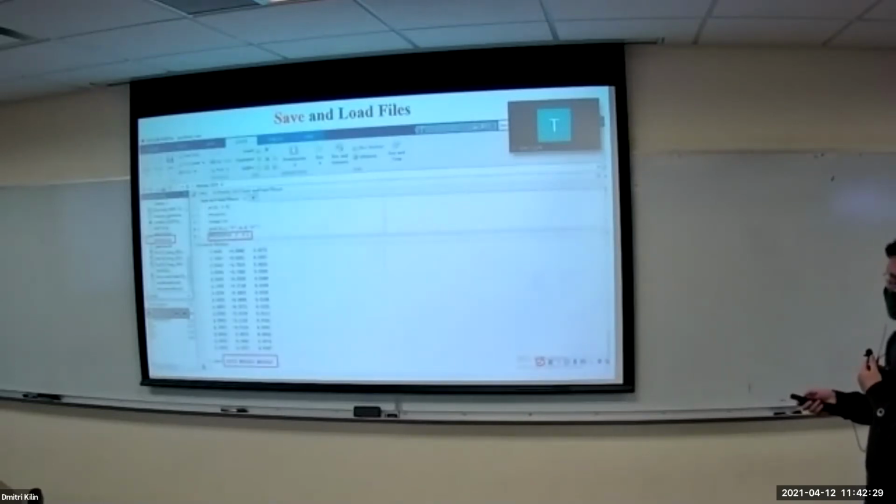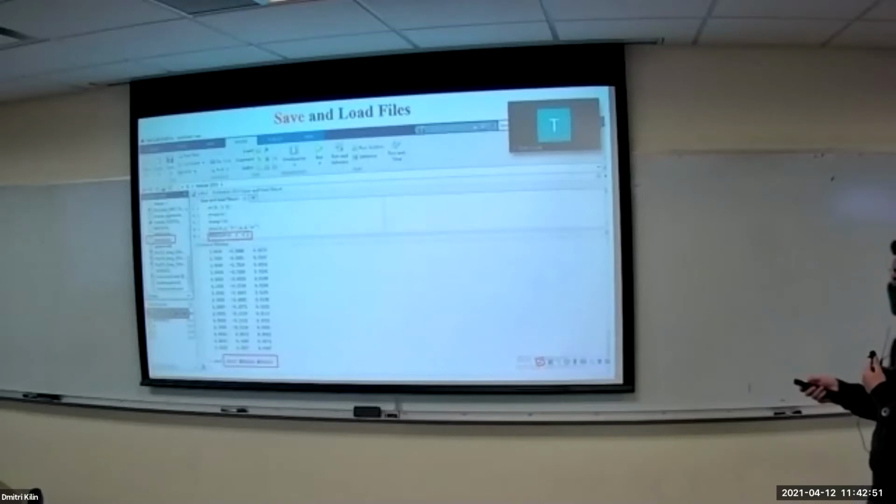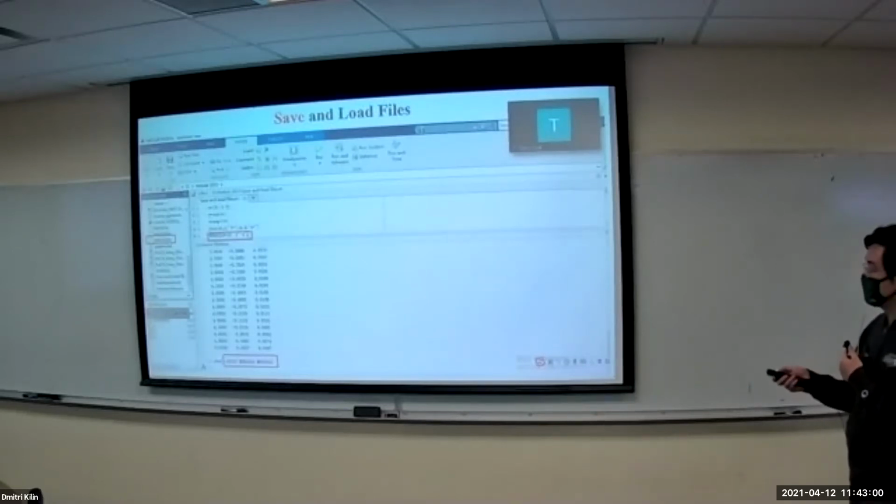Next, for the data, if we want to save the data, we just put save space minus ASC double I. Here I named the data my data 3. The my data 3 in the command window should be exactly the same as in the editor window.